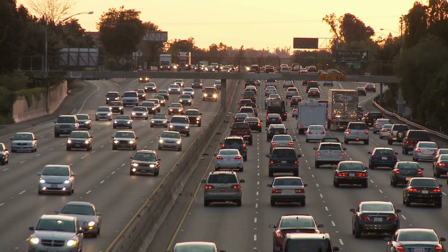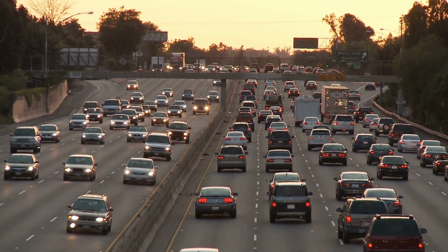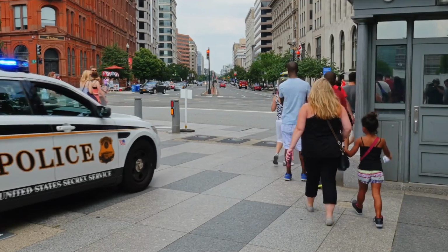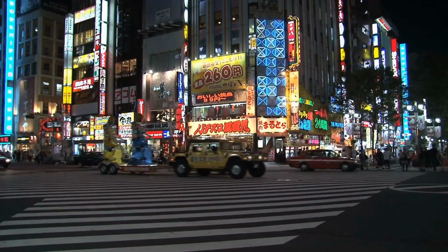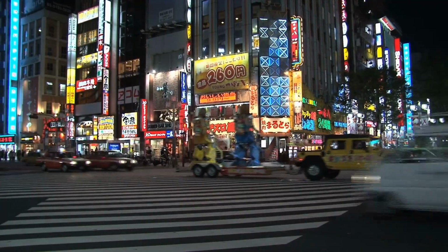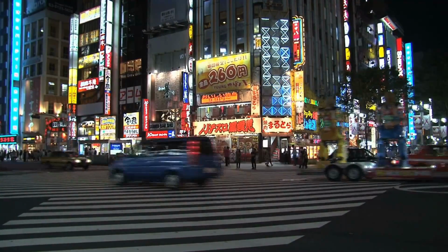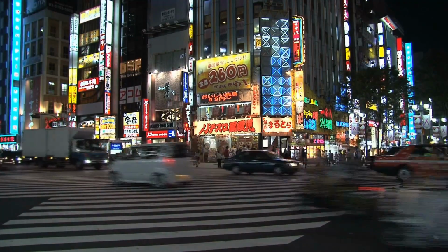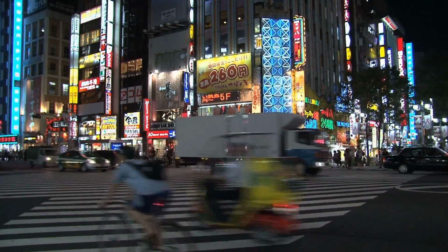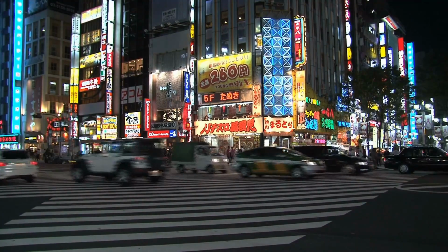Examples might be recognizing line information, so you make sure an autonomous vehicle stays within its lane. It might be recognizing things so that you won't collide into them. You might want to use it for an occupancy grid, so using some sensors that are short range and other sensors that are long range, and using sensor fusion to pull that all together and say, okay, these are the spaces that I think in my world are occupied versus these are the spaces that I think are unoccupied, and we can use for path planning to route a path from point A to point B.